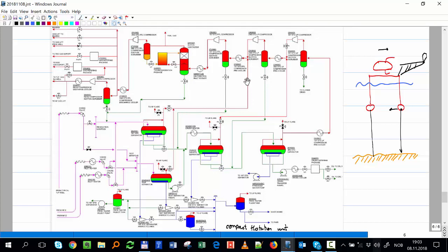And then I have a cooler, and then this famous scrubber, and then I come to a compressor, the first stage. The first stage comes to the dehydrator right away. I send the clean glycol, with not much water, from the top going down, and here it comes out. That's why you have the change of color: you have rich glycol, and then lean glycol at the top. Before compressing, the pressure is enough to use it for the turbine. Here at the top you see fuel gas.